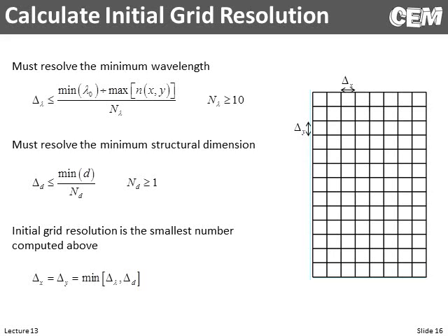It's up to you to figure out where that trade-off is. But convergence is the way, the rigorous way to determine these numbers. Everything else that I'm going to give you are just rules of thumb so that you can make a really good first guess as to grid resolution and stuff like that.